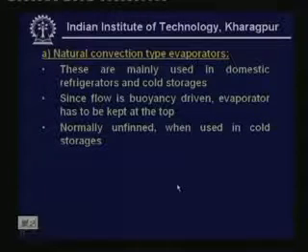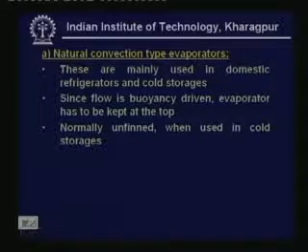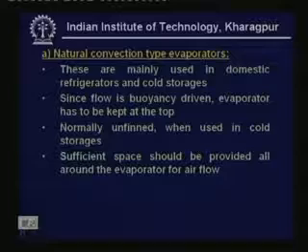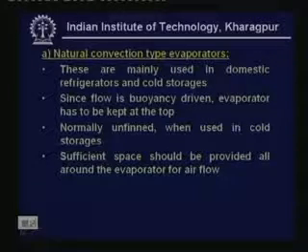Normally, these are unfinned when used in cold storages. As I said, these are mainly used in domestic refrigerators and cold storages. In domestic refrigerators, fins are added, but in cold storages, fins are not used. Sufficient space should be provided all around the evaporators for airflow.